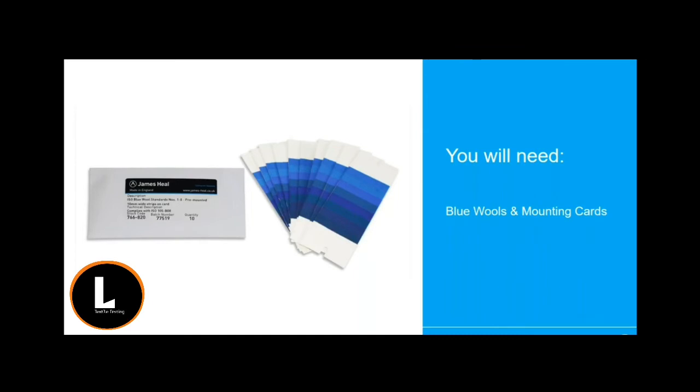You will also need blue wools and mounting cards. There are two types of blue wools. There's the European blue wool standards, which is ISO 105 B08, and American blue wools from AATCC. The popular testing standard, ISO 105 B02, allows the use of both of these wool types. It must, however, be made clear that the results from different sets of references may not be identical. So we would recommend to use either one type or the other, especially if direct comparisons are to be made.